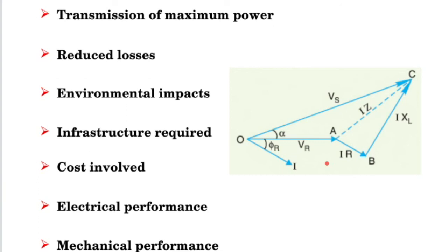As the MVA increases, we will see an increase in current. That will cause a lot of power loss in the transmission line. So if the reactive power is too much, we put reactive power supplying equipment in the system, meaning we can put some capacitor banks to balance